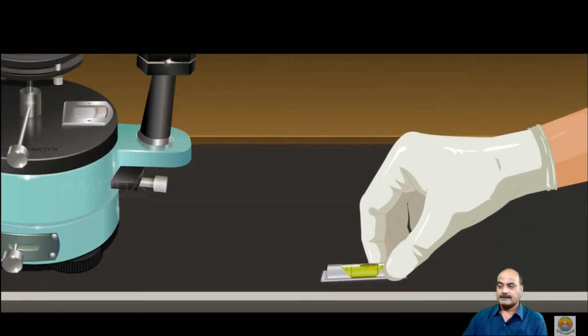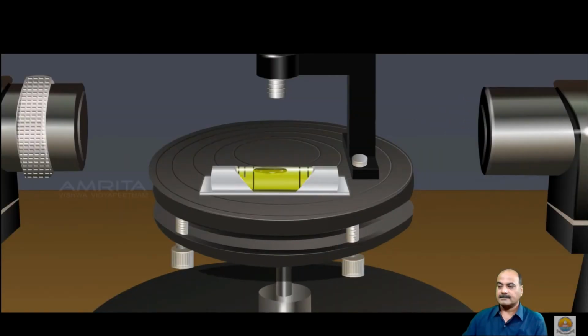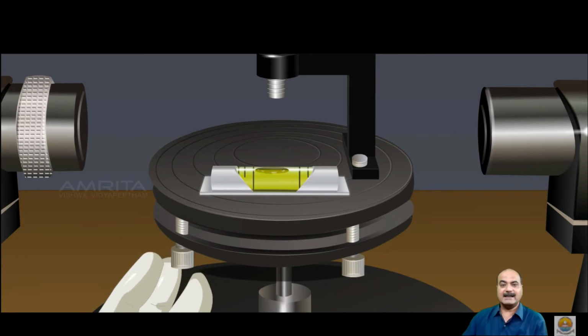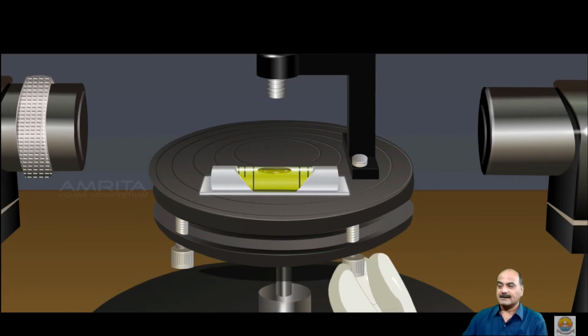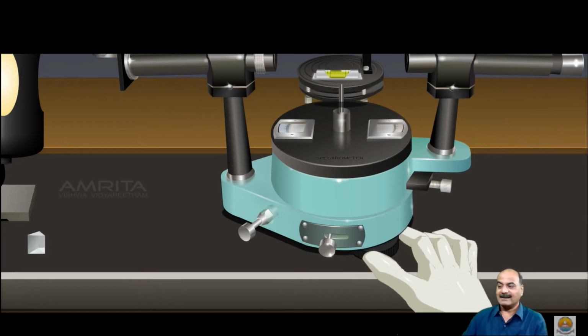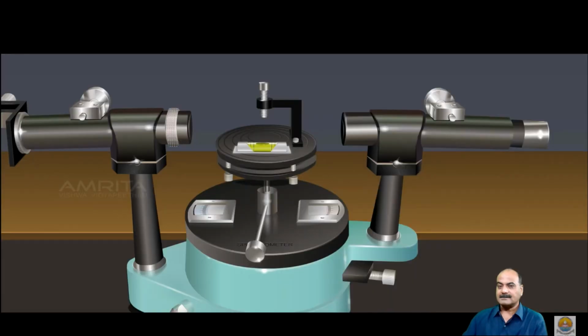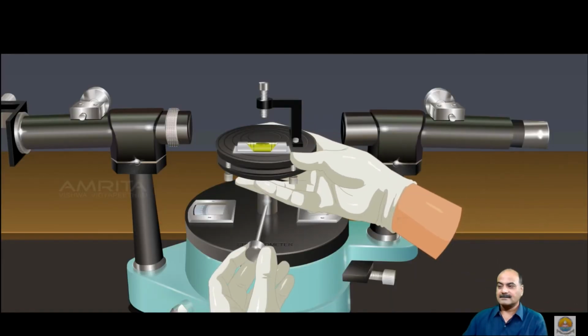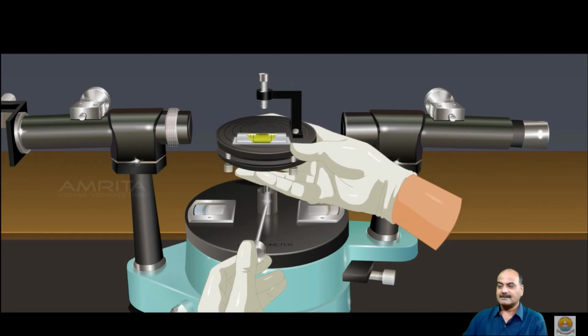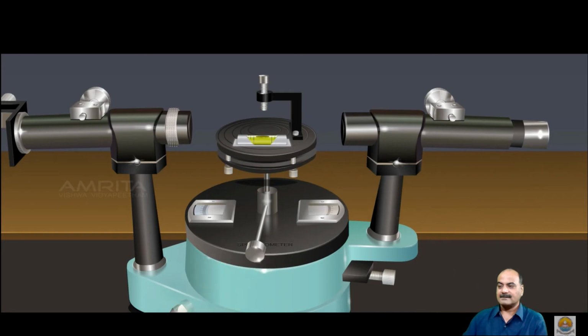Place the spirit level on the prism table. If the bubble of the level is not at the center, adjust the leveling screws to bring it into position. Also, use the base level adjusting screw to adjust the spirit level. Before going to the next preliminary adjustment, make sure that the bubble is at the center of the spirit level. Loosen the prism table fixing screw, level up the position, and place the prism table just below the line of the collimator. Then tighten the screw.